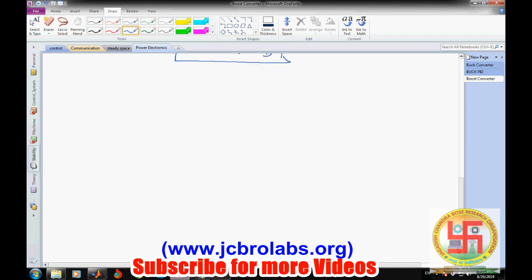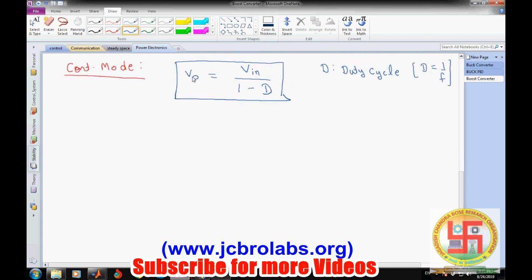Okay, so from here, if we have specified the amount of output voltage we require and the amount of V in, we can identify what the duty cycle of the wave should be. Okay, this is wrong. Duty cycle is not 1 by F, sorry for that. Duty cycle is equal to T on by total T. That means T on by T, or T on into F, because 1 by T equals the frequency. Sorry for that.